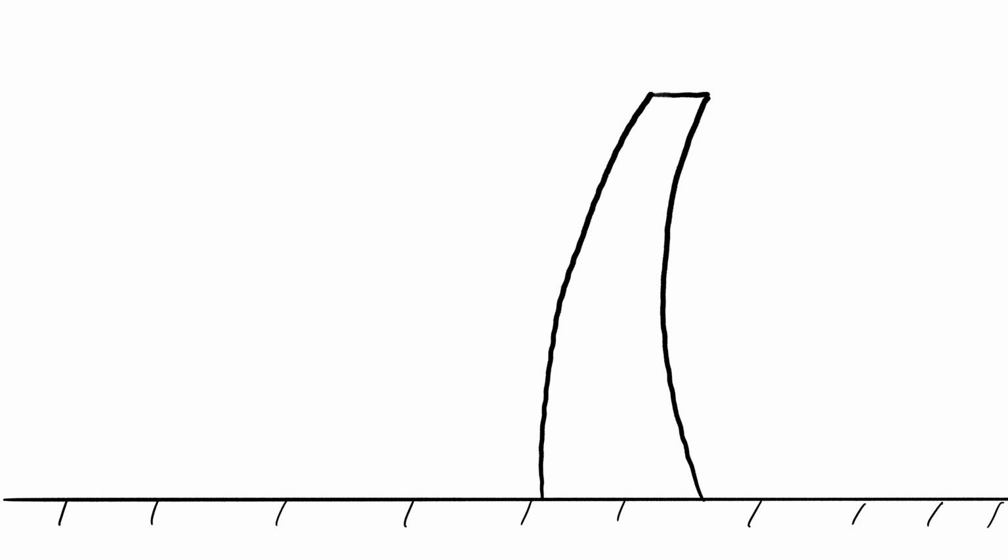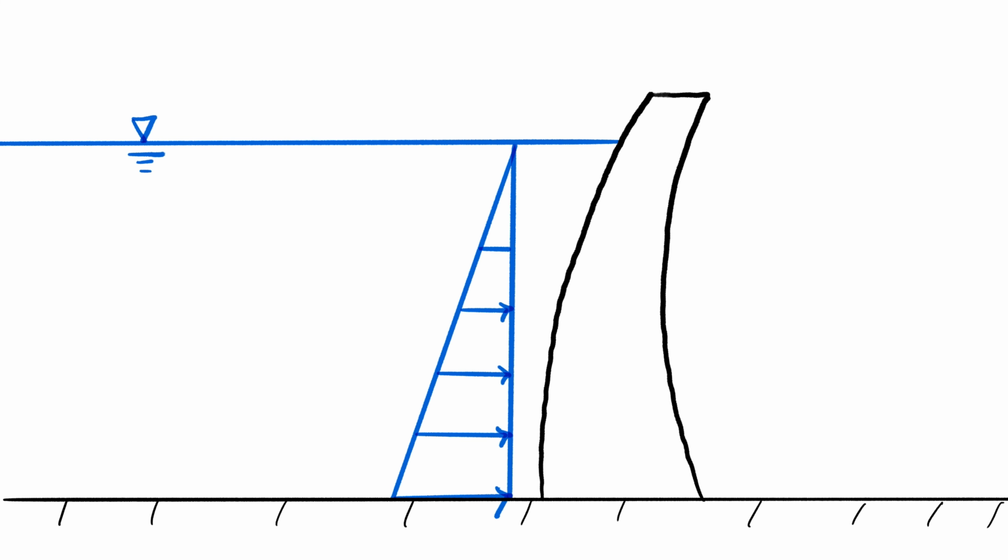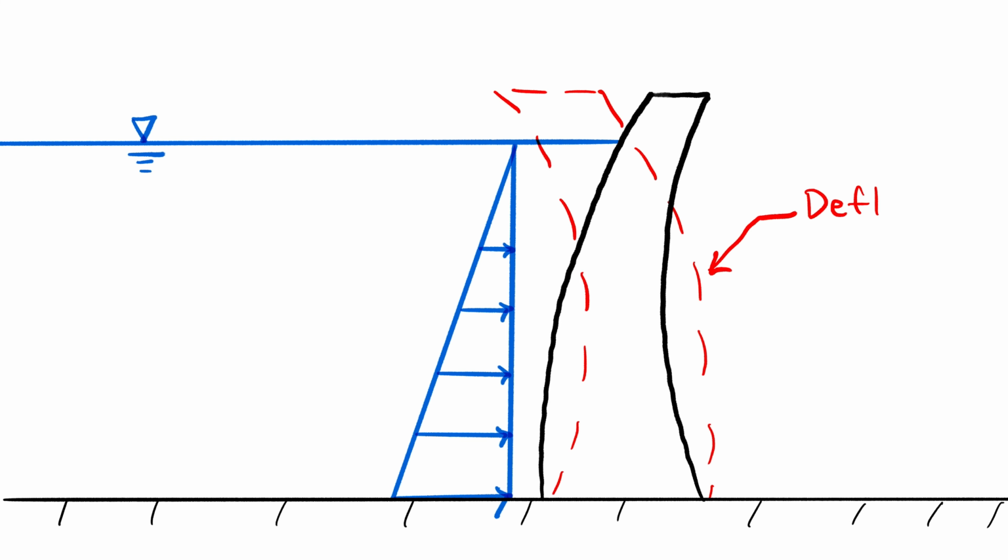An arc dam is literally a dam that's arced. It's curved upstream such that the force of water is pushed against the arc. This causes the dam to compress, which actually increases its strength. It's important to note here that concrete is strong in compression and weak in tension.